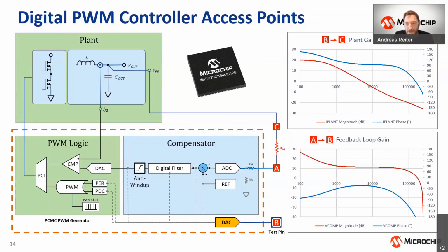So the big challenges we have in super high density power supplies or high voltage designs is actually that injection point. So in the first step, we're trying to get rid of that requirement that we have somewhere in our circuit, buried in our feedback path, a specific location where we have to put in a component and where we have to put all the probes. So eliminating that is the major goal, so that we are pulling this over into some safe low voltage section of our design, which is easy or easier to access than the rest of the circuit, and especially the power filter section.